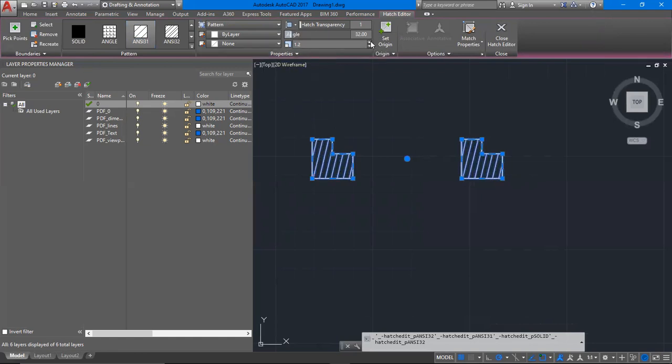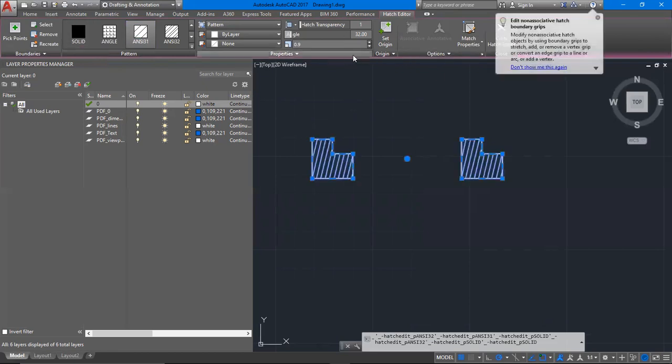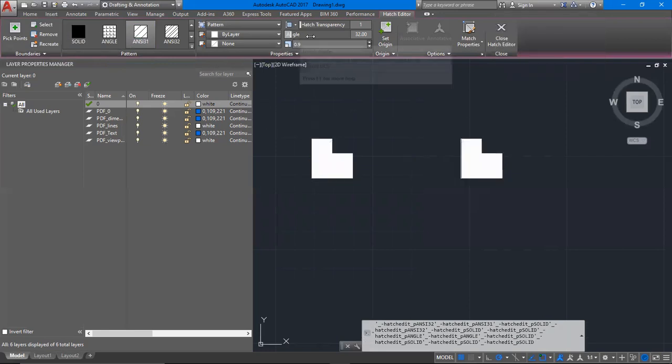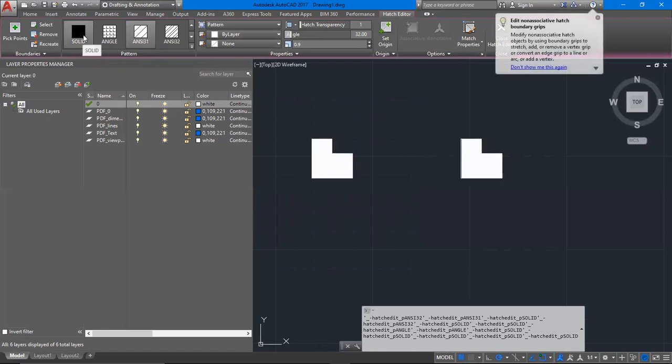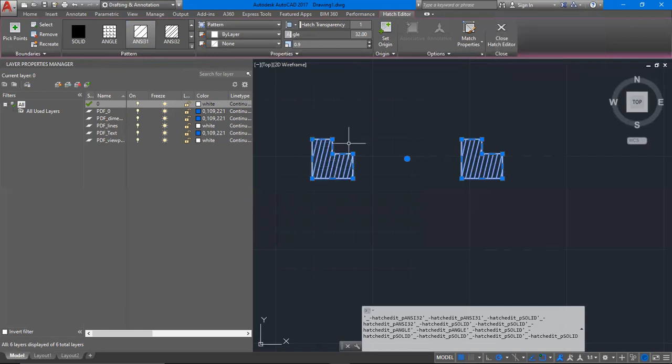Again, you can also do some scaling. You realize that those lines are being scaled out, and they are also being scaled in when I go downwards. So you realized when it was a solid color, it did not work because some of these commands don't work depending on the type of hatch you have. Like for solid, you may not edit a hatch for a solid color because how will you do the angle? I mean, you see the orientation of these lines is the one that changes when I adjust the angle.